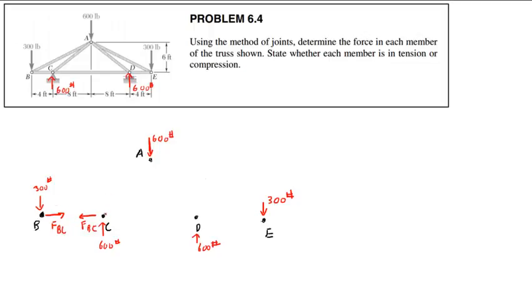And look, initially I am drawing this in tension. So the question is, why are forces coming away from joints? Why is that tension? Well, if you consider a member like this and joints here, if I have a tension force on this member like this, in turn, the joints will be pulled like this. So this is a tension system. So I show all of the forces as tension initially, which means forces coming away from joints.